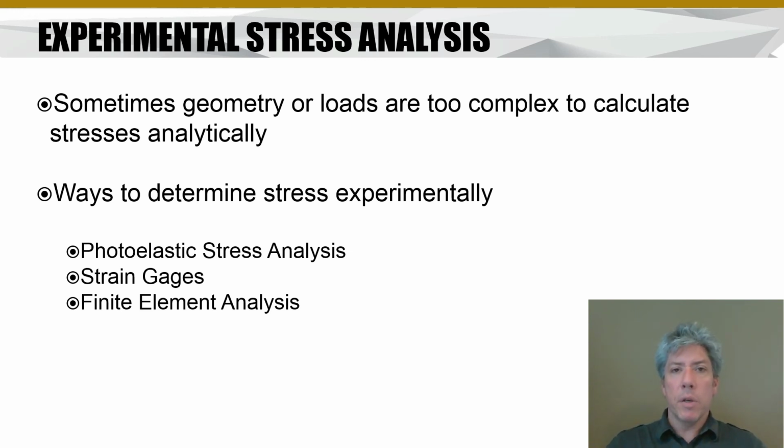But probably your go-to tool for complicated geometry will be finite element analysis. Now there are others. You can use photoelastic stress analysis. I'll show you some slides on that in a minute. And you can use strain gauges for measuring stress, well, actually measuring strain at points, and using the Young's modulus you can then figure out how much stress there is. But most of the time you'll probably turn to a computer simulation and finite element analysis. It's become so common and ubiquitous, I'm sure you'll end up using it at some point in your career.